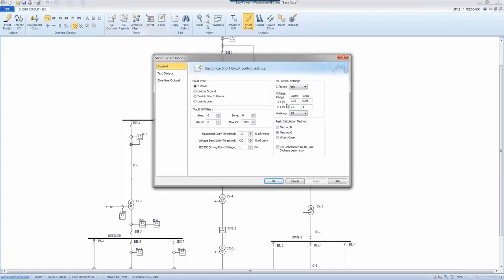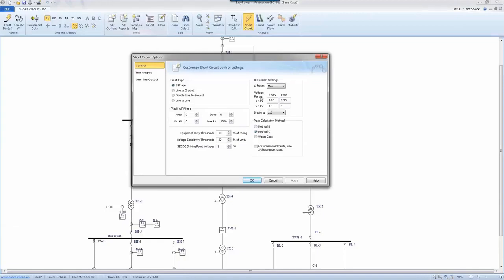When we use Cmin or Cmax, we will change the cables and transmission line impedance values. For Cmax, we try to minimize them. In order to minimize them, we replace them with the value of the impedance of that cable or transmission line at 20 degrees, which makes it minimal. It really lowers it, and we look at the formula for that. When we go to Cmin, we try to maximize the impedance of the cables and transmission lines, which means that we will increase the temperature for those components. So this is where the C factor is implemented, in fact.